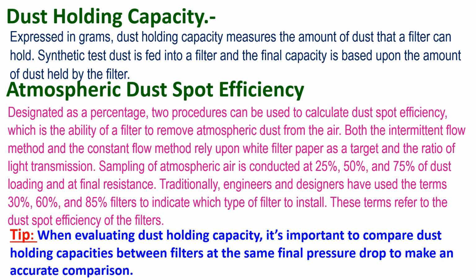Tip: when evaluating the dust holding capacity, it's important to compare dust holding capacities between filters at the same final pressure drop to make an accurate comparison.